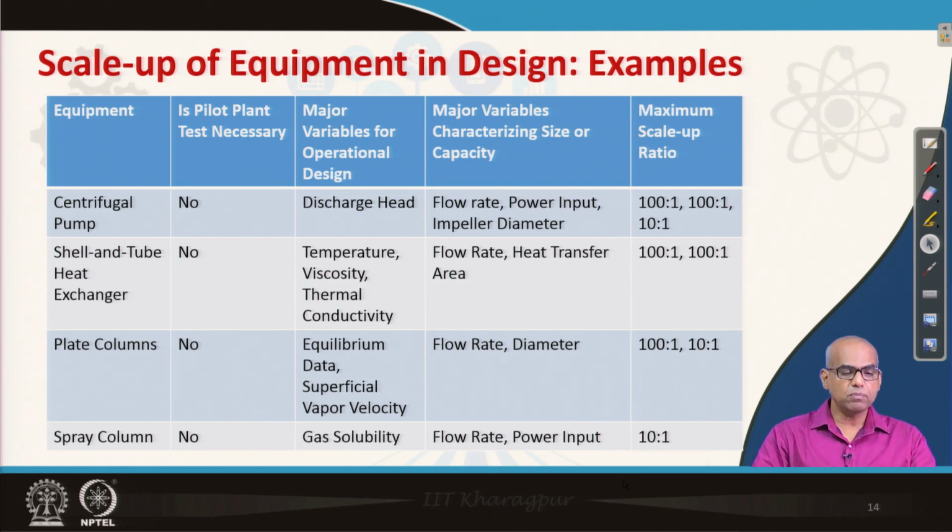So, centrifugal pumps, shell and tube heat exchanger, plate columns, spray columns: for these equipment, you do not need to perform pilot plant tests. The table also gives you major variables for operational design, major variables characterizing size or capacity, as well as maximum scale-up ratio.